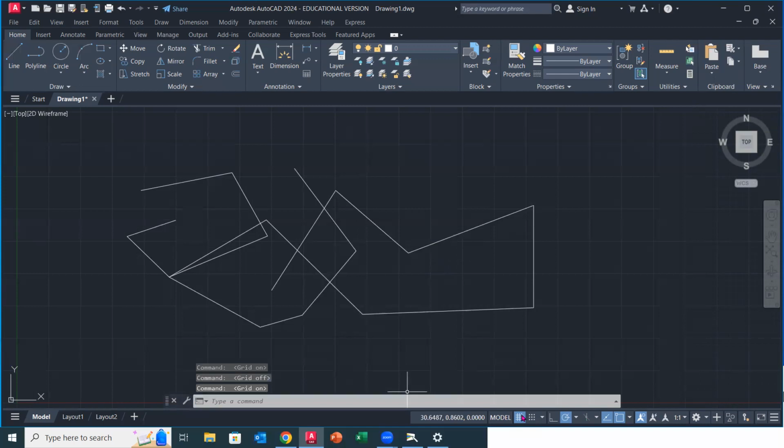Now, this may not be evident on my screen here, but if you look at your AutoCAD screen, this first one is called grid. When you have it in that bluish gray mode, you're going to see grids in the background here. Do you see that? They're very faint on your screen. That's like drawing on paper, grid paper. That's all. Again, it just gives you a little bit of perspective. They're a drawing aid when you're starting out. It's a good thing to have.